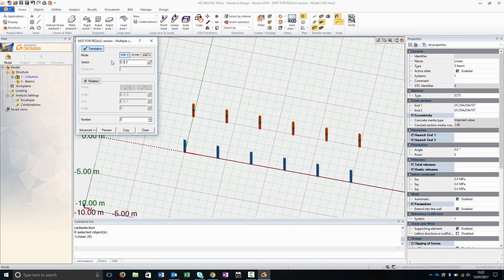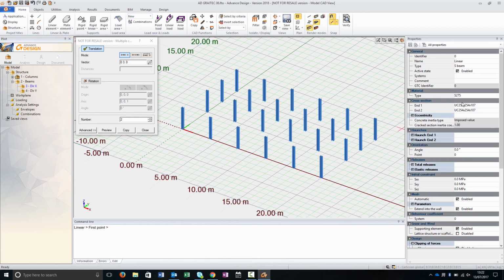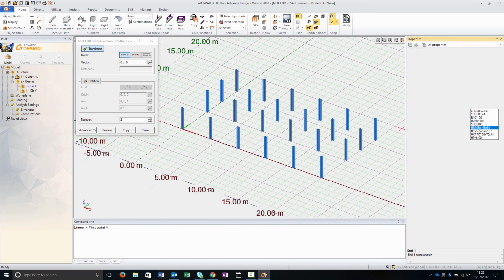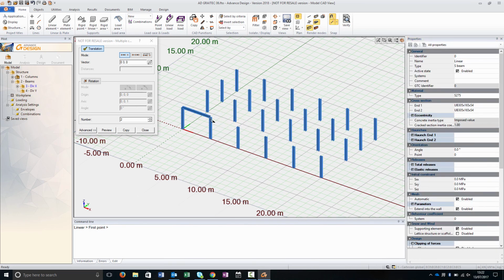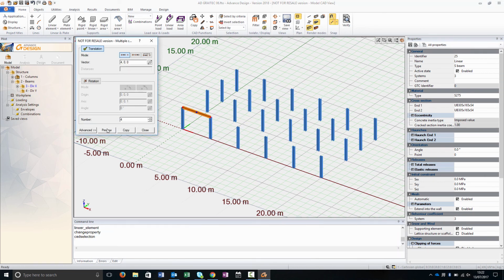When we use the cut function, the preview helps us to understand if we are working correctly. We set different subsystems in our project to help us to select and amend elements and to analyze the results. To help us to draw our structure, we can also use non-structural elements such as points, lines, grids, and load areas. Load areas are non-structural entities that spread the loads between the elements we define them on.